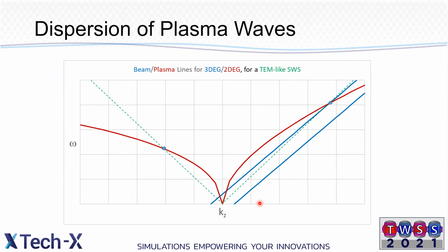What does that look like? Well, if we had a drift velocity like a vacuum electronics beam, we would have one of these blue lines, and then the plasma wave splits that blue line into two very close lines. And then one of those blue lines would intersect with maybe some kind of slow wave structure, represented by the dotted green line.